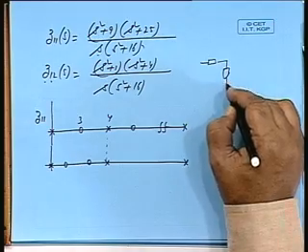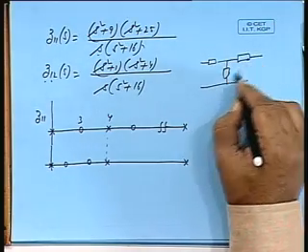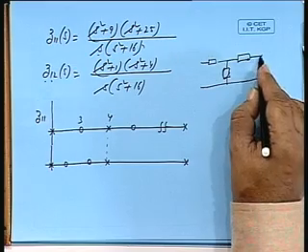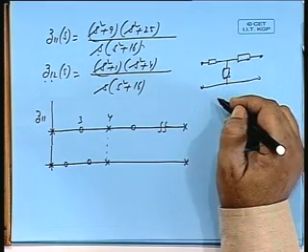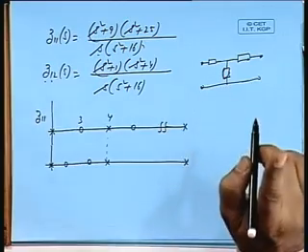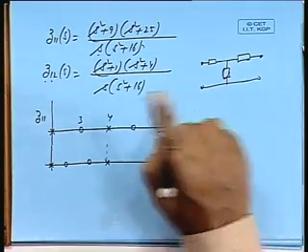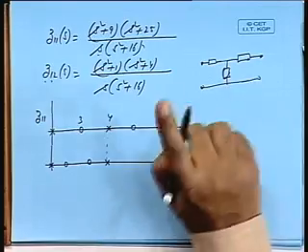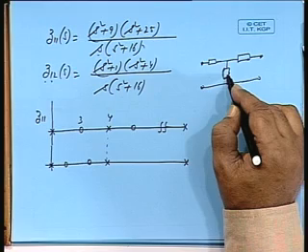They need not be positive real functions. Z12, by repeated star delta conversions, you got Z12 as this impedance, but this need not be a positive real function. Only thing is the numerator and denominator coefficients must always be positive. When you go for repeated star delta conversions, you must get all the coefficients positive, but repeated conversion of star and delta does not guarantee positive real functions. That means the element may not be realizable.